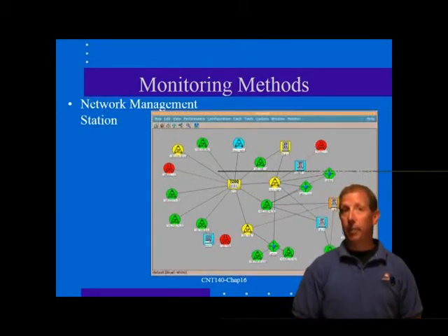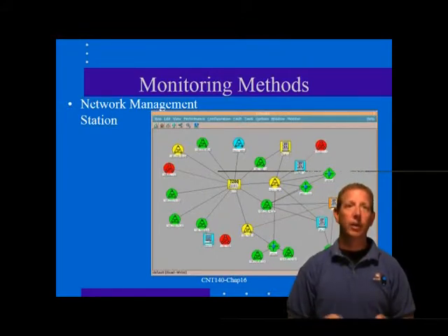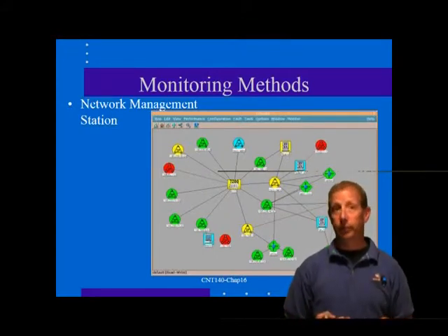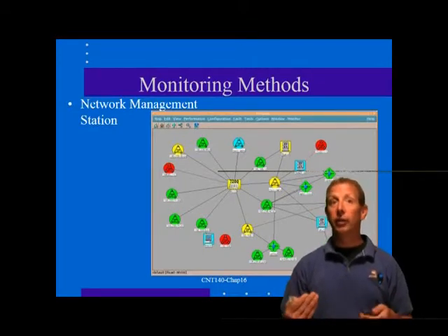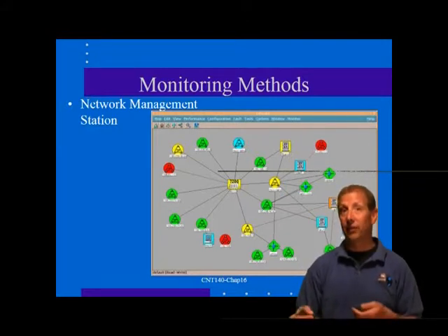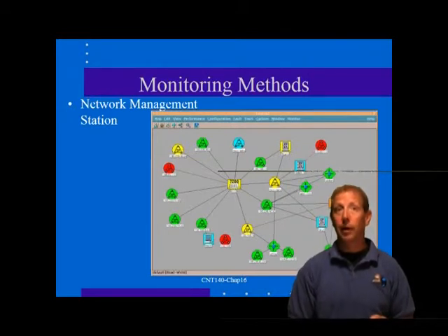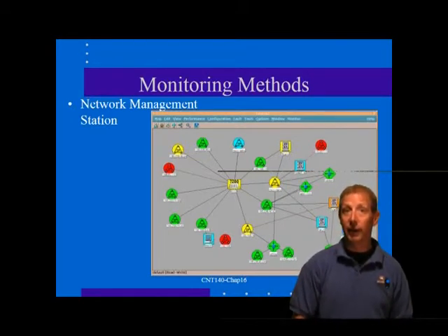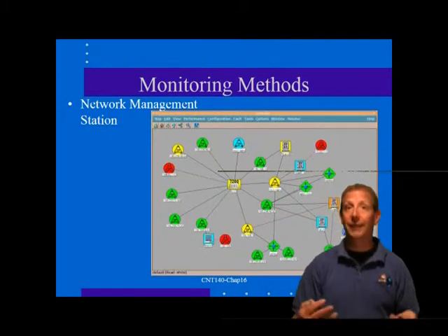Let's look at physical cable monitoring. Physical cable monitoring on installed LAN wiring systems presents some very special problems. Most of the simple ways that can be used require that the monitoring be performed by the connected LAN devices, such as the 10/100 Base-T or token ring hub. The hub monitors the condition of the link and then reports by indicator lights at the front panel of the hub or by sending messages to a remote monitoring station.